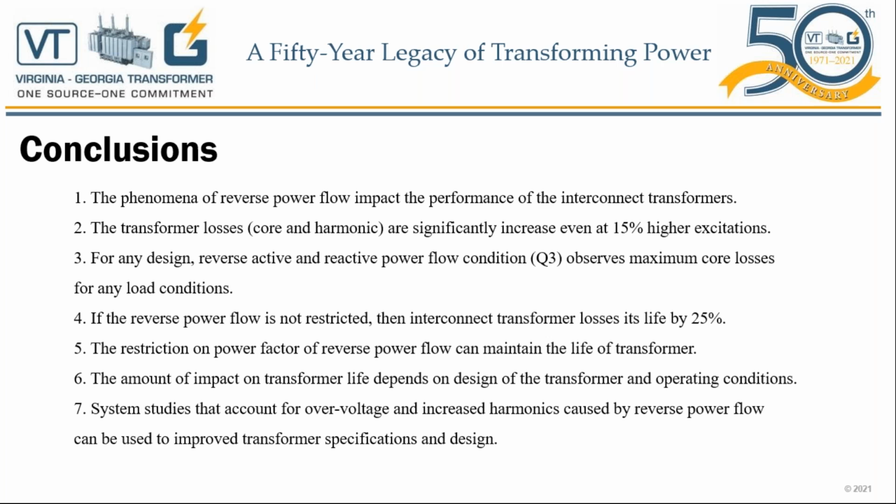Number one, the phenomenon of reverse power flow impacts the performance of the interconnected transformers. Number two, the transformer losses, core and harmonic, are significantly increasing even at 15% higher excitation. Once again, as a reminder, most transformers are designed to run at 110% with no load, 105% excitation with load and a 0.8 power factor.